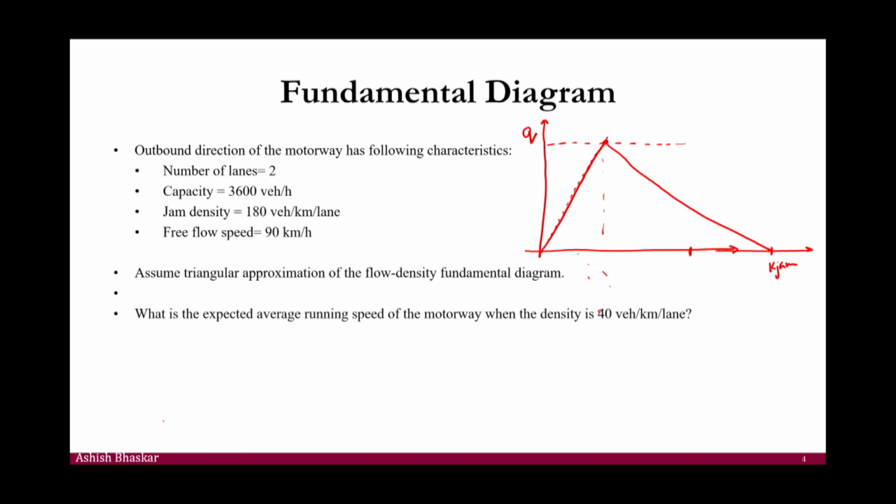But if I had said there is a drop in the capacity by 20%, sketch that, then you would have to drop this point by 20% and then draw this line like this, or whatever form it is, right? The point is, whatever shape you draw, talk about the assumption. In this case, the assumption is there is no capacity drop, and let's work with that. But that is going to complicate more. I have not talked about the more complex ways of representing the fundamental diagram, especially with capacity drop and other phenomena like hysteresis. Let's make it simple.